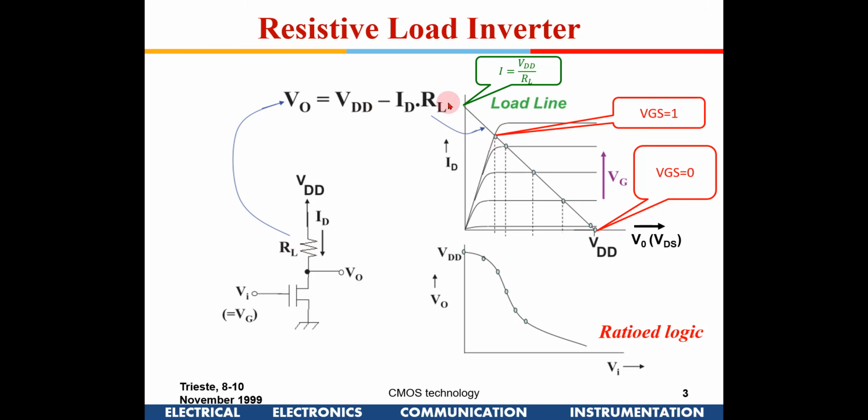So you see it is intercepting the load line at this particular point. If I draw a horizontal line here, it will not touch VDD. So I have some VOL, which is not 0, but slightly higher. From there I have to bring a line towards the x-axis, so that will give me a VOL. So this much residual voltage is available out here, and that is VOL. So this is how there is an issue with this transistor. Is it okay? Correct?